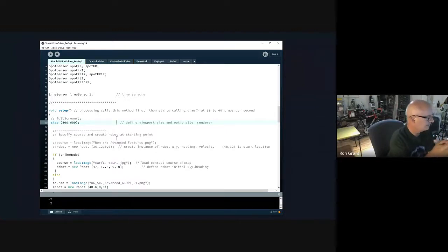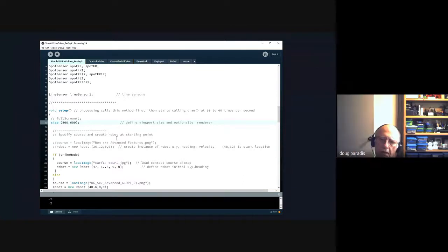Now, if you wanted to implement a lower level implementation, but in our case, we're giving high level rate of turn and velocity. So we really don't care about our wheelbase. It's independent, given at that level.